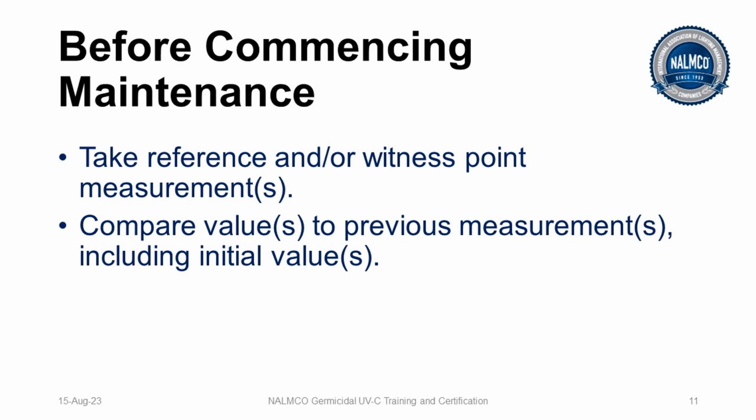And hopefully that value was recorded when the unit was put in. So you can see, okay, yes, I've lost 20% since the installation. After cleaning, it's only down 10%. So your cleaning was correct.